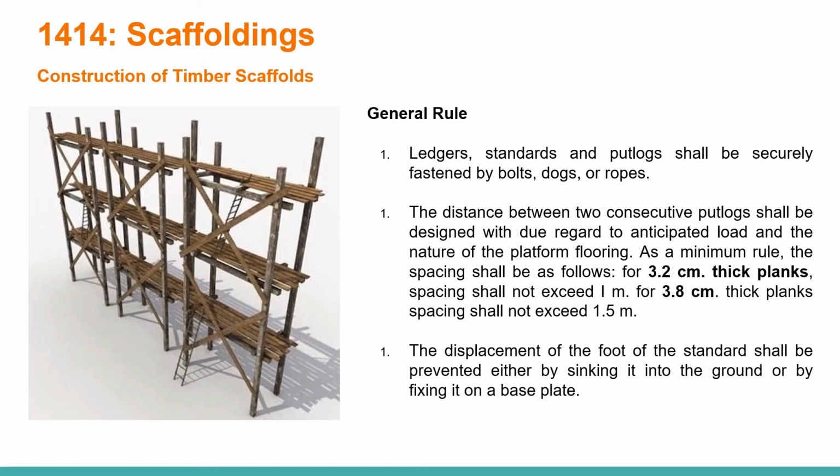For 3.2 centimeters thick planks, spacing shall not exceed 1 meter. For 3.8 centimeters thick planks, spacing shall not exceed 1.5 meters. Also, the displacement of the foot of the standard shall be prevented either by sinking it into the ground or by fixing it on a base plate.